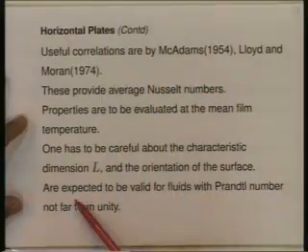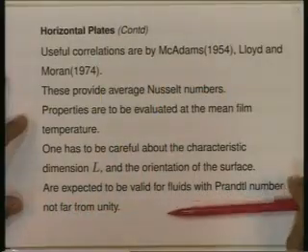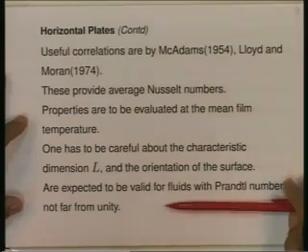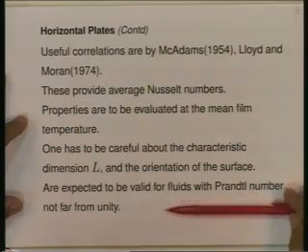These are not valid for a very wide range of Prandtl number. The experiments have been done essentially with air, sometimes with water, and hence the correlations are expected to be valid for fluids with Prandtl number not far from unity. Air and water are okay, but they may not be valid for, say, liquid metals or for highly viscous oils.